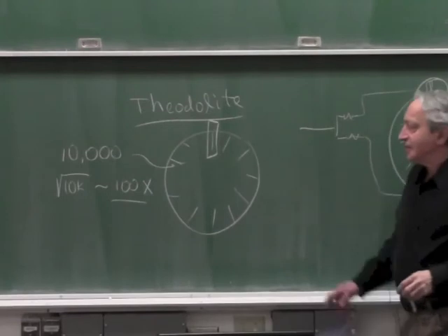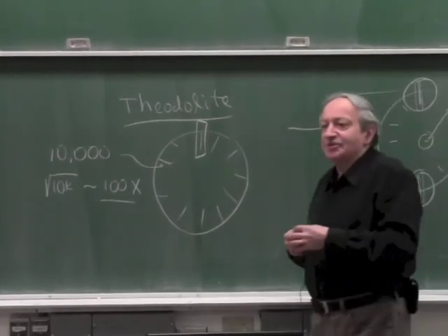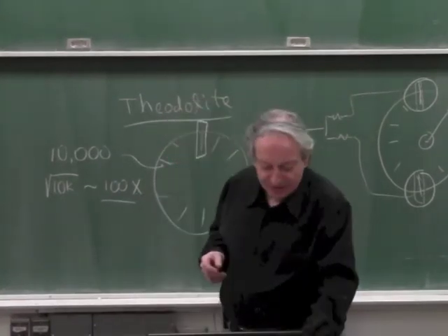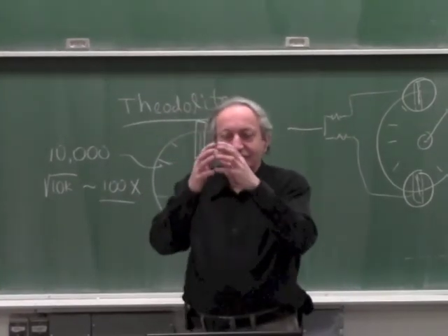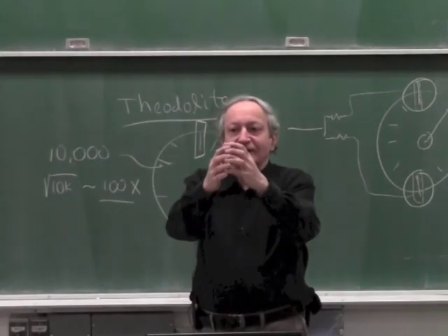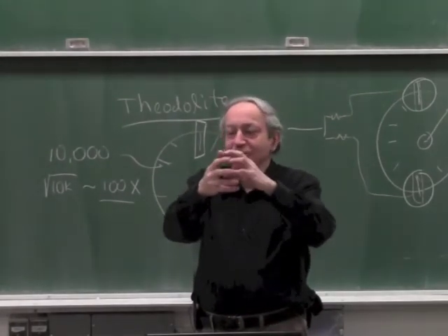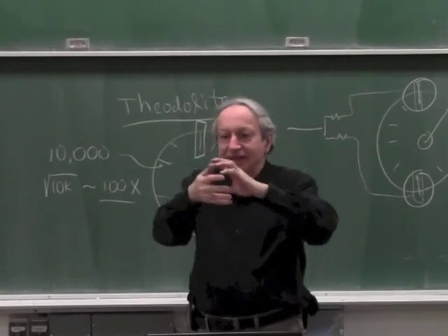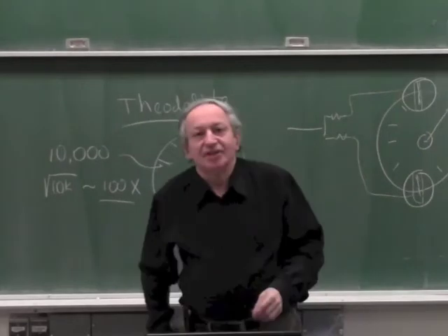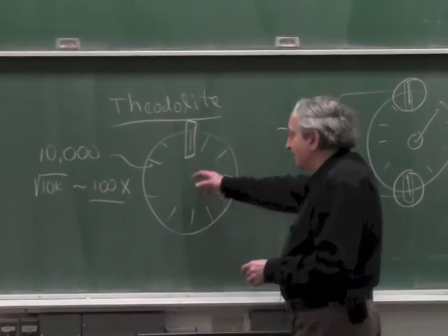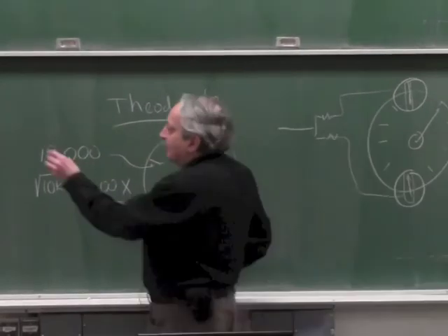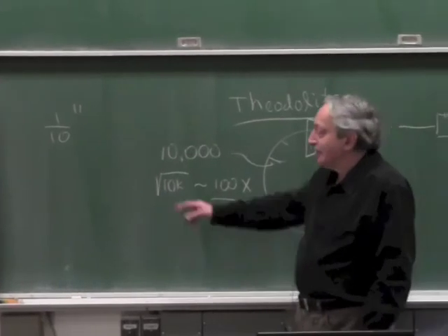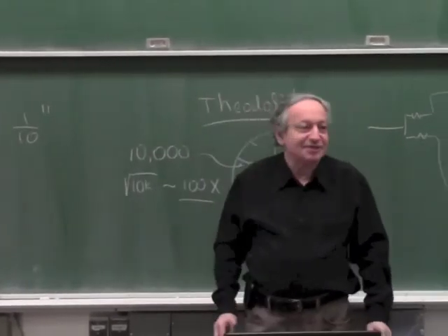And I also mentioned that this idea is the basis of the most accurate angle standards in the world, which instead of encoders use two phase gears. So there are two gears meshed like this, and you move them out and remesh them and remesh them. Typically the gears have 360 teeth, so when you mesh them again and again, they average all the teeth. And using this method, either in an encoder or in meshing disks, you can get to 1/10 of an arc-second accuracy, which is a very, very small number if you start thinking what it means.